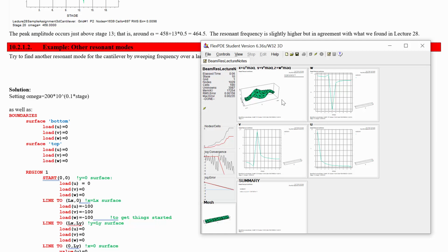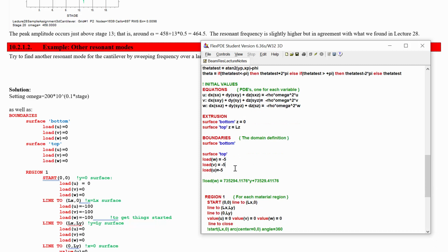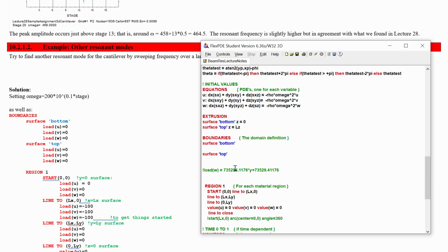So to stop a lot of these complementary modes from messing with the solution, if you'd like to specifically look for something in X, you can set up the loading so that you're going to be finding only that as your excitation. And a trick here is we'll go on the far X surface, which is this one.